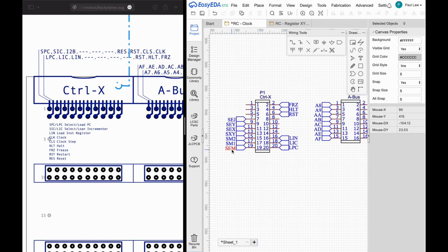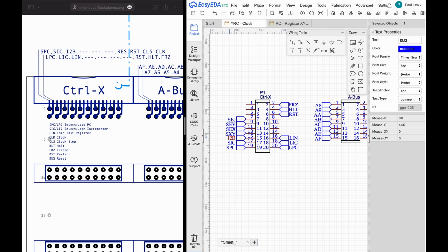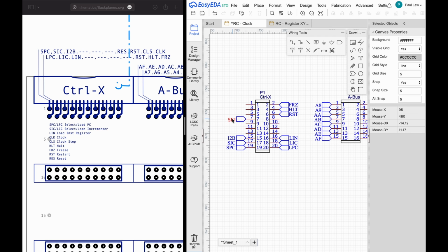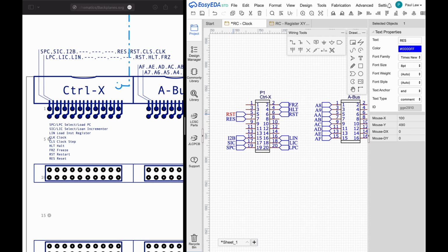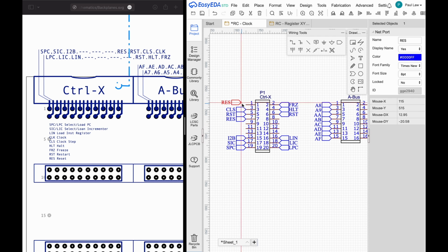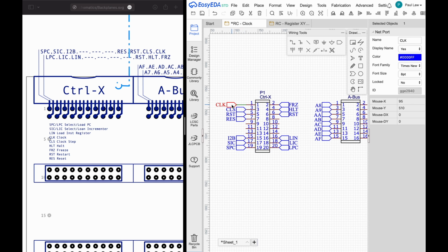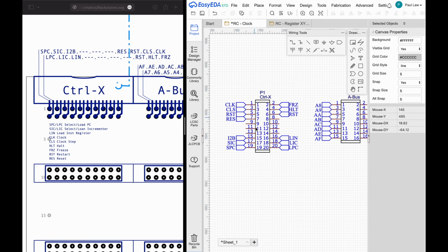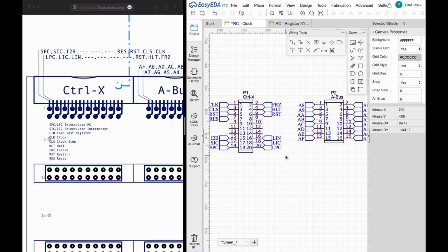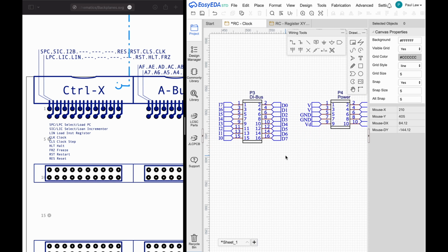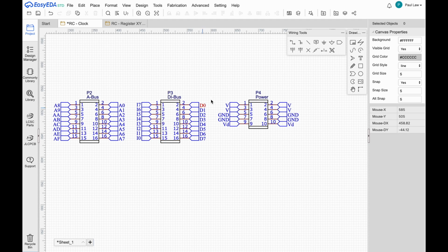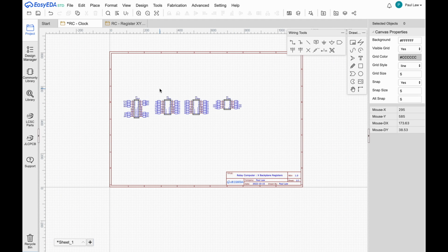With those done, I can repeat the left-hand pins, although here there's a different mix of unused and used lines, but no problem as I can just copy the connection ports. So that's our set of connectors, and each of those flag-shaped things will act as a link to anywhere else in the schematic where we use the same name port. This means we can pick lines up on other sheets and reduce any clutter on the schematic as a whole.